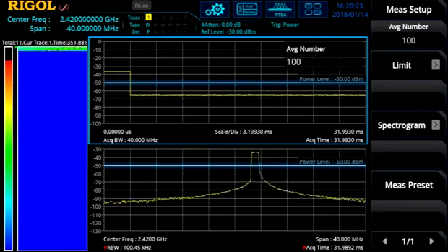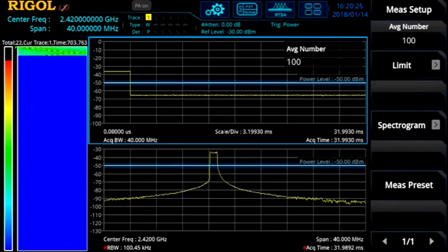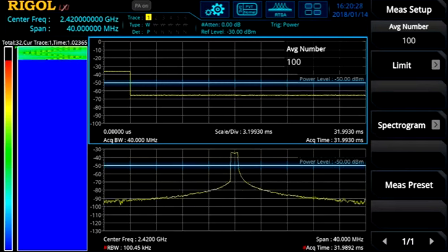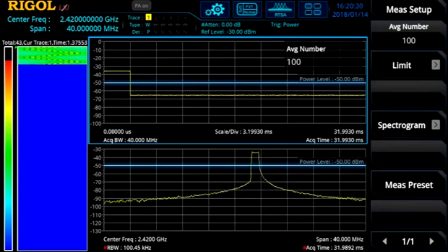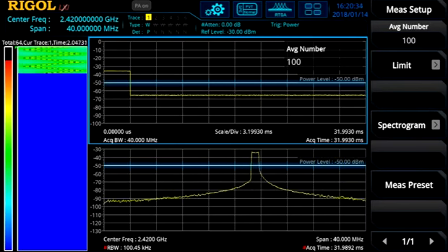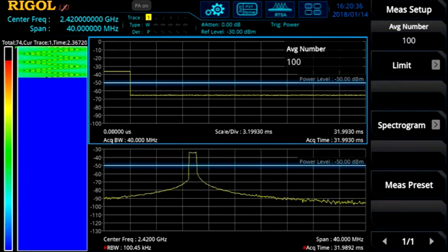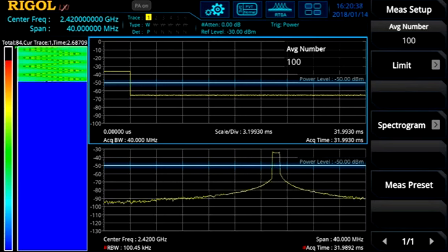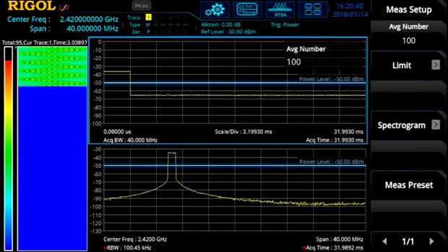We can also trigger on the power output here and return to the full span to view this signal in time using our PVT normal spectrogram view. Now we're viewing time in the main window and capturing each pulse. This is the power over the entire span, so it shows the pulse width of each event even though the underlying carrier frequency is changing.